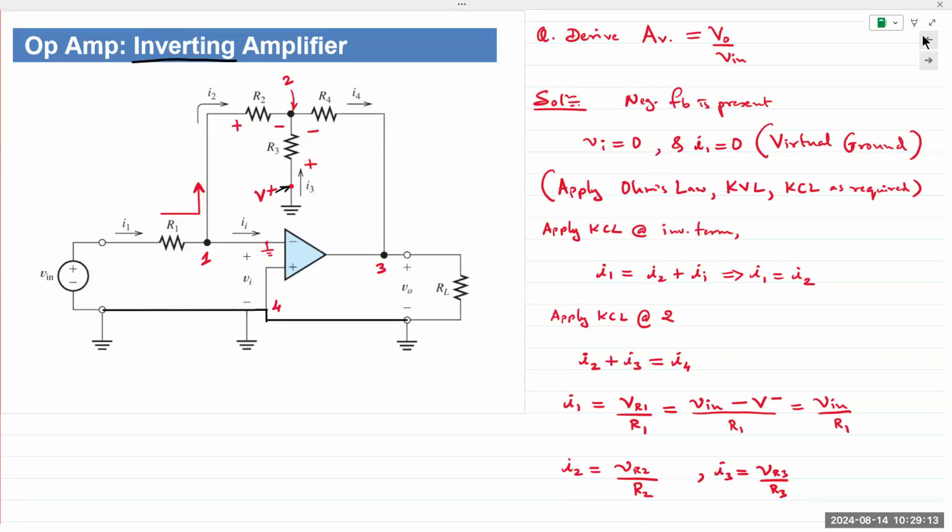But again, that's a different discussion. So it's kind of like conflicting conclusions at the same time. If it suits our purposes or our model, we can say it's virtually shorted. If it doesn't, we can say it's virtually open. For the purposes of our analysis for inverting amplifiers, we use the model where they are both virtually connected together, virtually shorted.